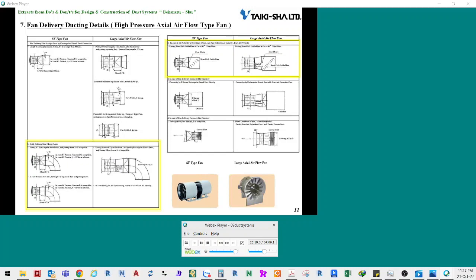In both cases, if a 4-pole motor is used, the diameter of the duct to be connected may be the same as that of the opening on the suction side. A straight duct also may be used. If a 2-pole motor is used, the extension duct with an extension angle of 15 degrees on each side must be selected.